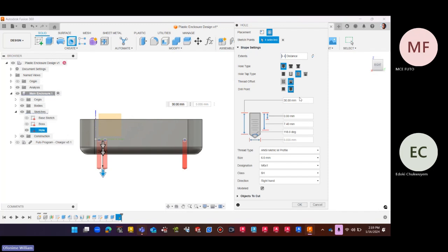Okay, no, I'll still use that. So we just come over to this point and select the depth of that hole. If you remember our boss, he had a height which was 12 millimeters. We still recall, the boss had as a parameter a height of 12 mm, right? So there's no way our thread will exceed where it is going to dwell in. So we are looking at possibly a 10.